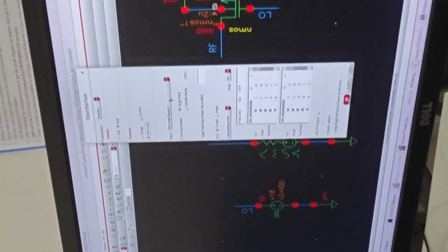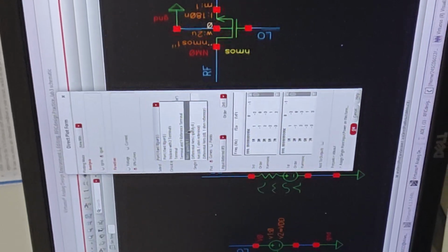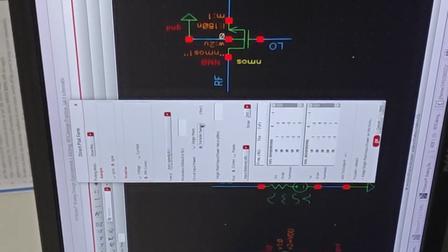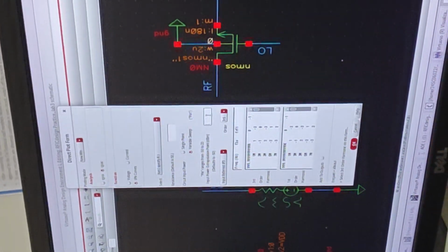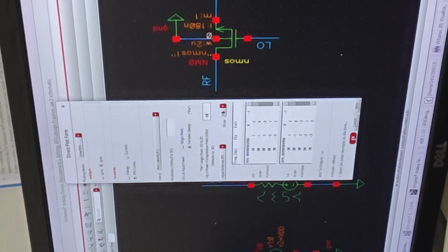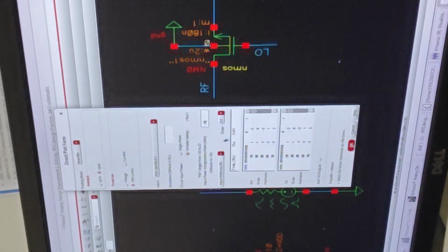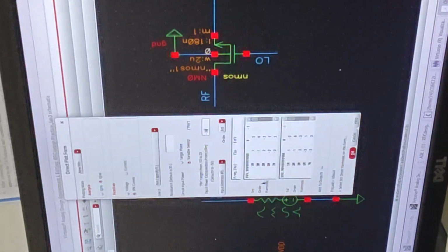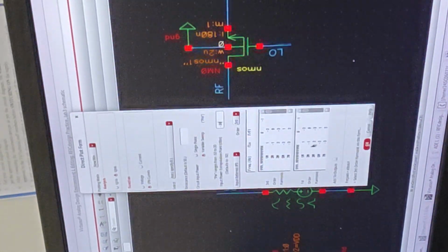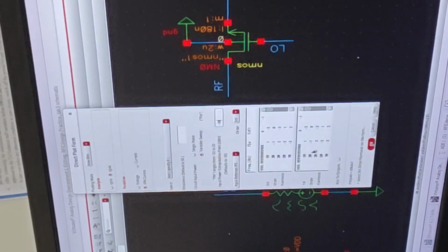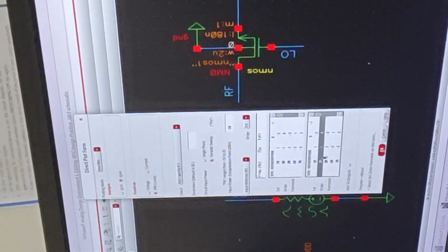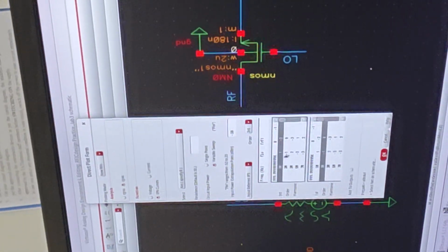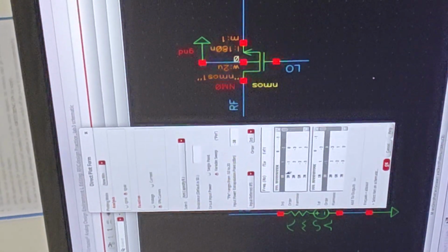So now go to the QPSS, IP curves, same as before, and we are taking a variable sweep. Let's say minus 30 dB. I wanted to extrapolate. So now here you need to select the first order harmonic and the third order harmonic. Now where is your first order harmonic? 3 megahertz, and the other one is 1 and minus 1 megahertz.